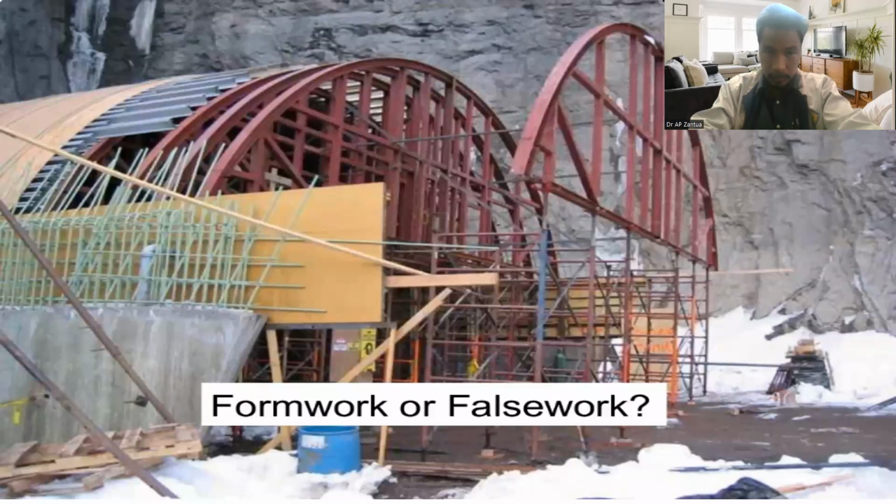So again, the most famous picture of formwork versus falsework. All of these are formwork, and this portion, these are the falsework. Okay, these are the falsework, and over this arc, they will have what? The flat surface for the introduction of wet concrete.